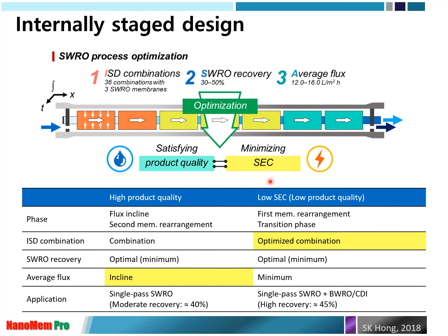So if you see this in the front part, there is a lot of fouling coming through this membrane, and therefore we utilize the very high rejection RO membrane module, and then most of the organics and the contaminants will be absorbed in these two modules, and then the less rejection RO module, the most relaxed rejection, which means the high water flux, can be allocated in this module.